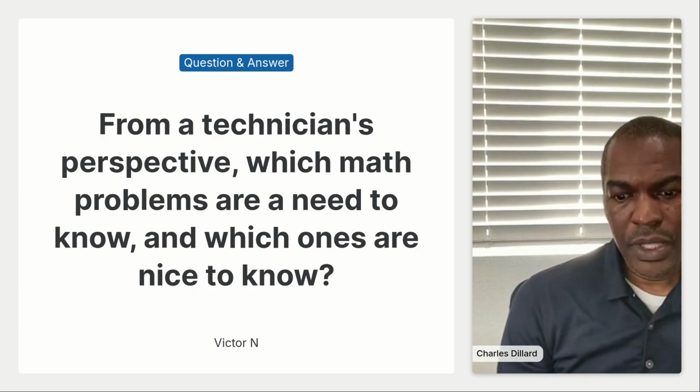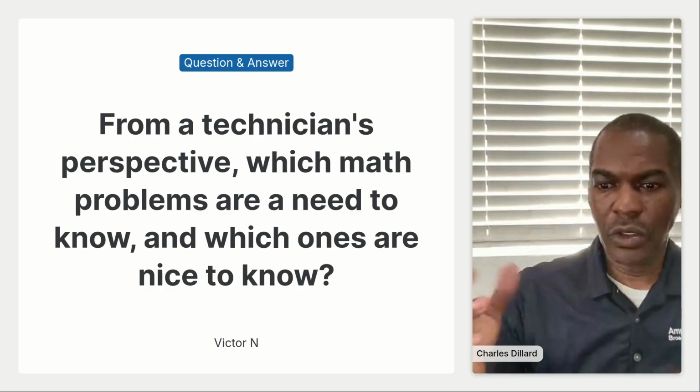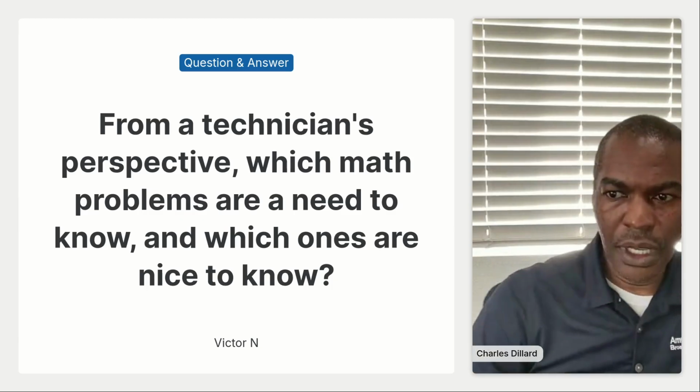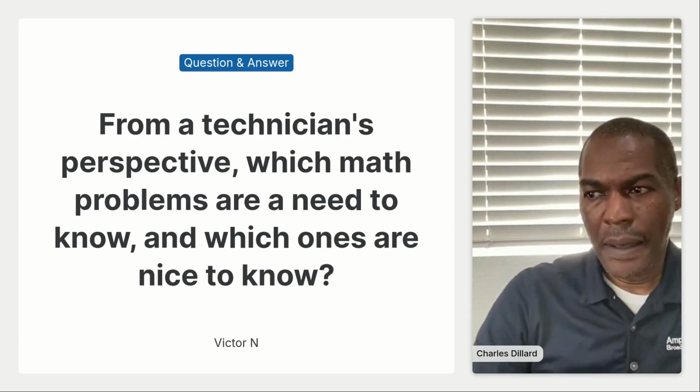If I'm looking at safety goggles, for example, and they're rated at a certain optical level, you want to understand, as you're dealing with fiber on a day-to-day basis, what lasers are hazardous and what lasers are even more hazardous. The stuff that we usually do in our industry is pretty safe because the light is contained in the edge of the connector.